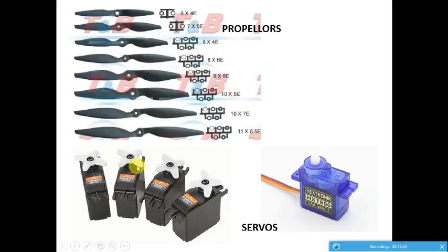Other things, these are high torque servos which are used to control the orientation of control surfaces, such as flaps, ailerons, rudders, elevators, or landing gear. Servos also have three wire inputs. The central one is for the signal controlling the rotation of the servo, and the other two on either side are a positive and a negative wire, which are usually connected to plus 5 volt and ground.